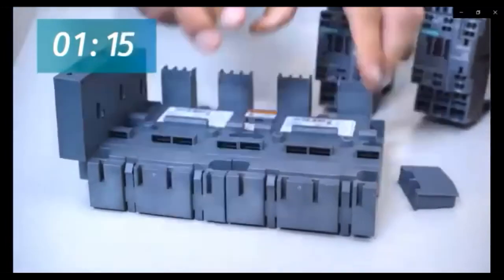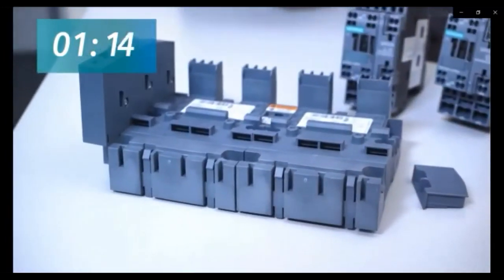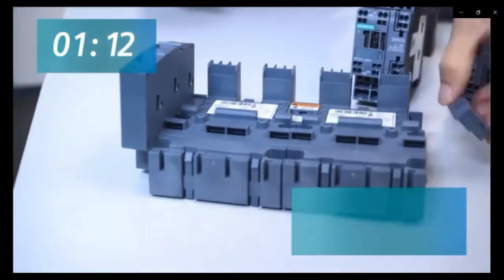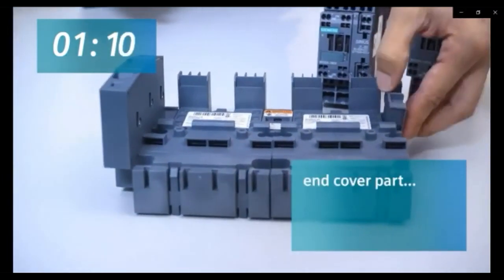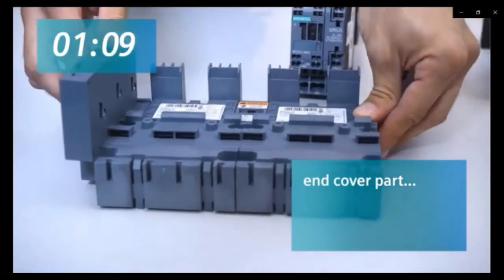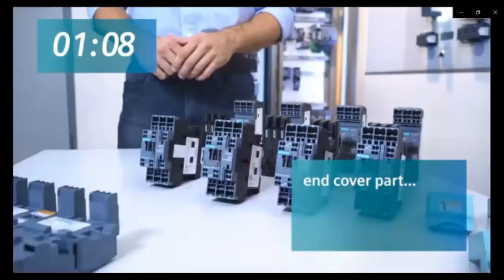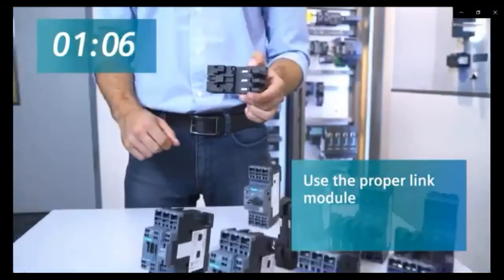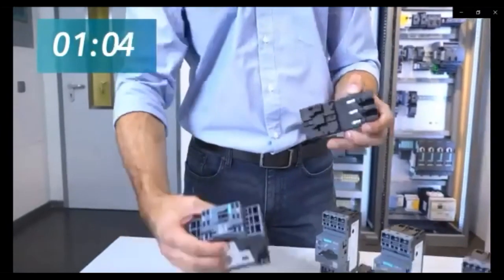You just need to align and push. Align and push. And please note that the infeed system will also work with screw-type devices. You just need to use the proper links. I'm now adding the base in the control panel by just snapping it down on the DIN rail. I'm adding now the 4 starters like so.